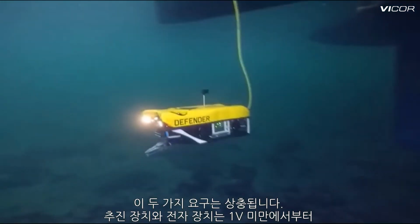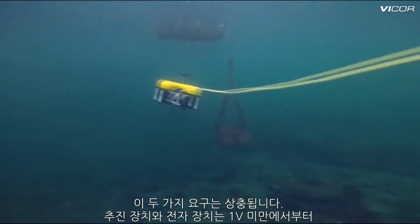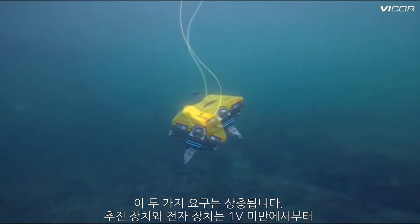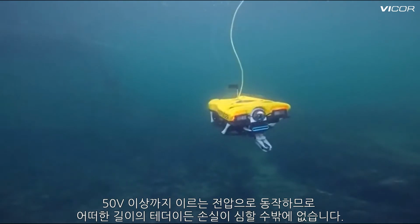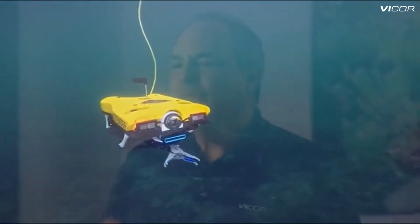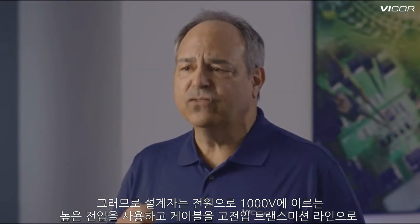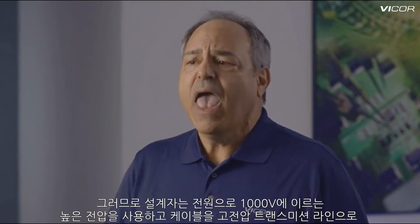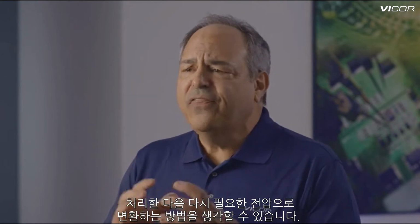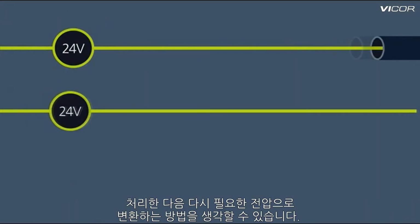These two requirements are typically at odds with one another, as propulsion and electronic payloads typically work at voltages ranging from sub 1 volt to over 50 volts, making any length of tether very lossy. This leads the designer to consider higher voltages up to 1,000 volts as a source and address the tether as a high voltage transmission line that then transforms and regulates back to the needed voltages on the vehicle.